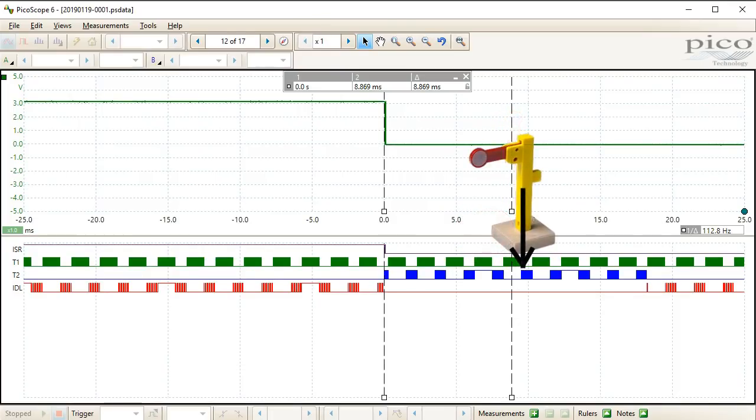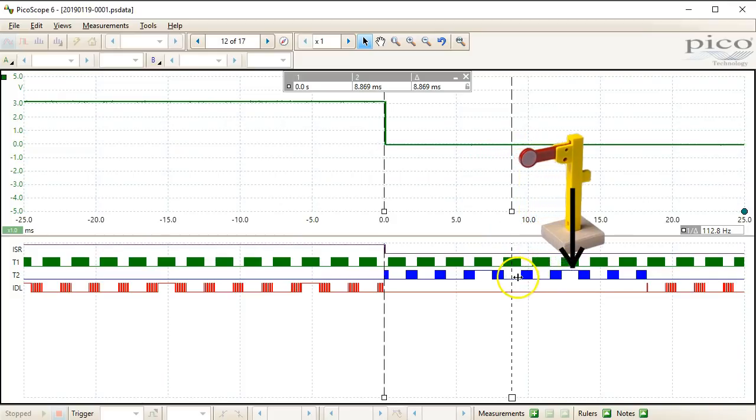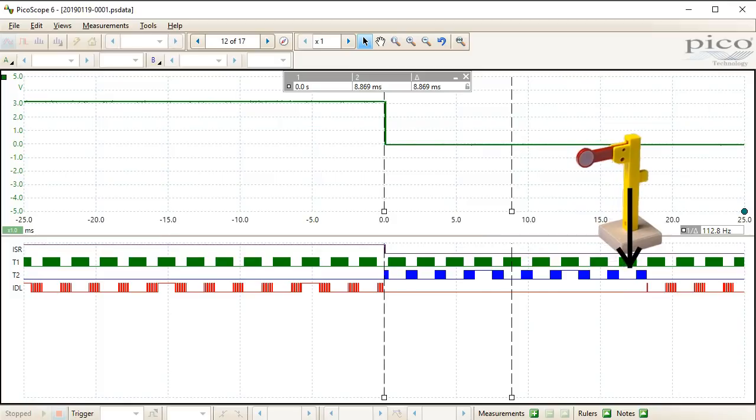This time the token was immediately available in the semaphore, so the wait operation just removed the token but didn't block. Blinky2 continued through the loop the second time. Eventually, Blinky2 looped back to the top of its while(1) loop and called the semaphore wait operation for the third time. This time, however, the semaphore was empty and so Blinky2 blocked.